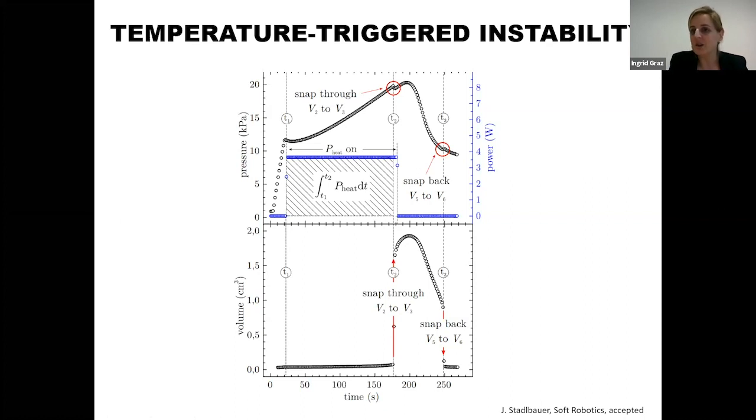When you look at the actuators, we always have a refill chamber. But ideally, you would try to seal it with something like parylene that's gas tight. It still has the mechanical properties to allow for the movement without hampering it, but at the same time seals it a little bit, because on the other side it's thick enough that you don't have so much diffusion or evaporation. The top membrane is maybe mainly the problem. But you could see actuation got better because the liquid was already in a heated state, and we did not see that much loss of low boiling point working liquid. I was surprised myself. I thought we would lose a lot more. But parylene solves this.